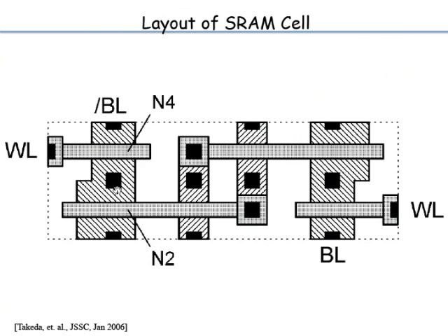Now, what are the transistors you want to match? There is a certain relationship you want to maintain between the strengths of the driver and the access. So previous layouts, which you can look up in the textbook, the driver transistor and the access transistor orientations were different. Okay. But here they are in the same direction. Similarly, PMOS is also in the same direction. So all this basically helps, everything kind of is related to everything else. So the variation effect comes down.